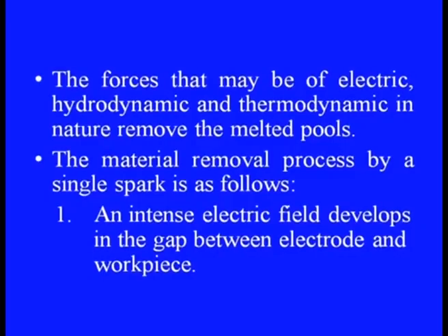Both tool as well as the workpiece get eroded. At the end of the pulse duration, a pause time begins. The forces that may be of electric, hydrodynamic and thermodynamic in nature remove the melted pools.